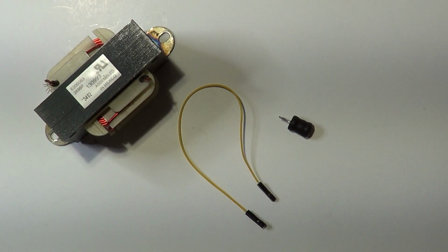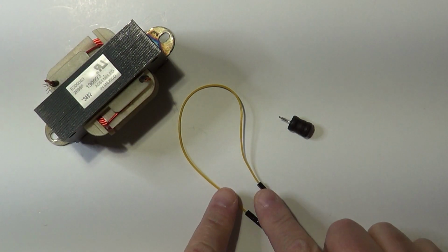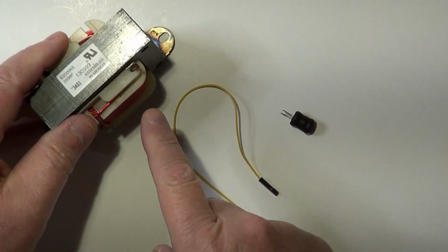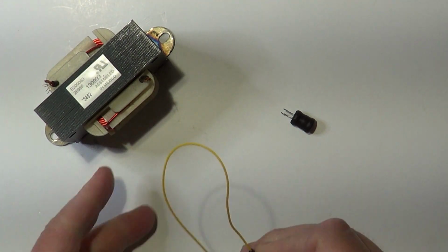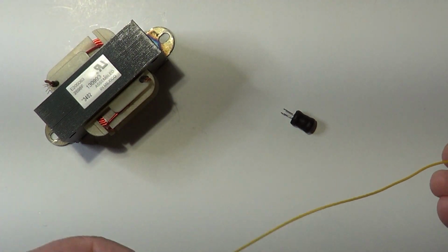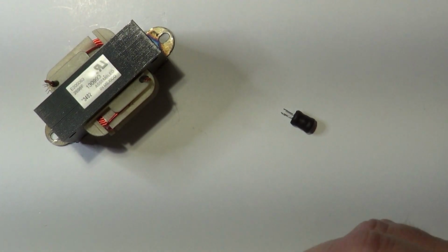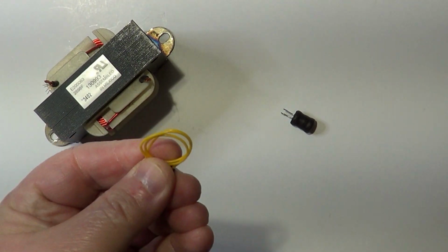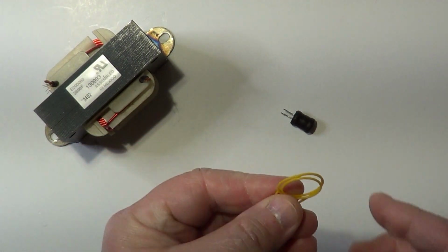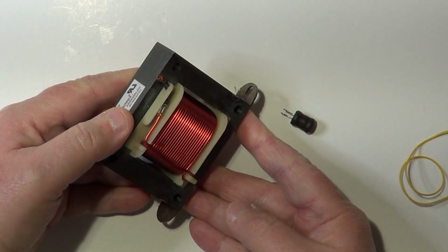Inductance is the property of opposing changes on the electrical current flowing through a conductor. Any conductor has an inductance, but depending on its shape and the vicinity to certain materials, the inductance can be very small or very high. A single wire has an inductance. If we take the wire and we shape it as a loop, the inductance increases. If we make several loops with the same wire, which we call a coil, like this, the inductance becomes even higher, and if we create a coil around a piece of iron, the inductance becomes much higher.